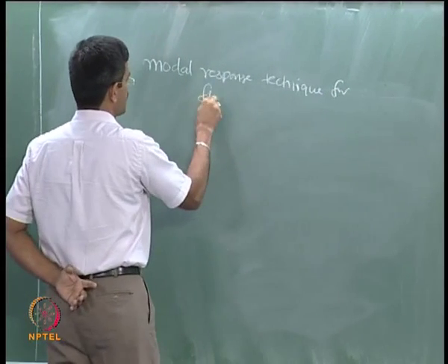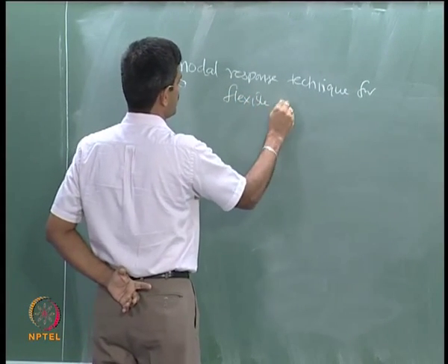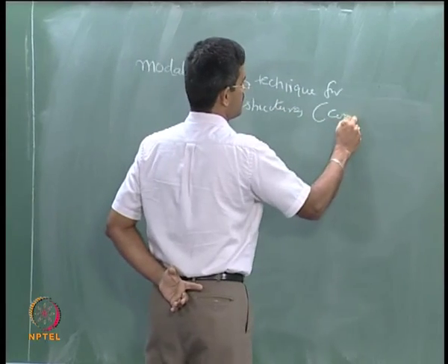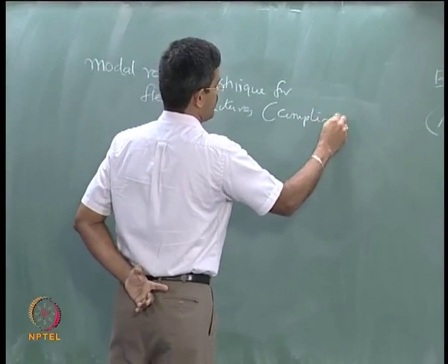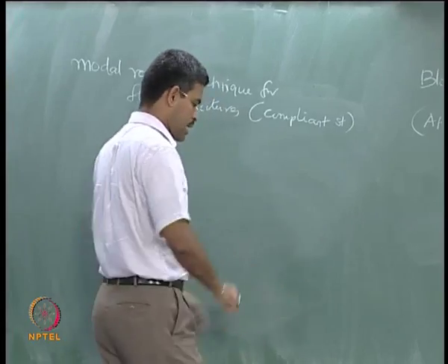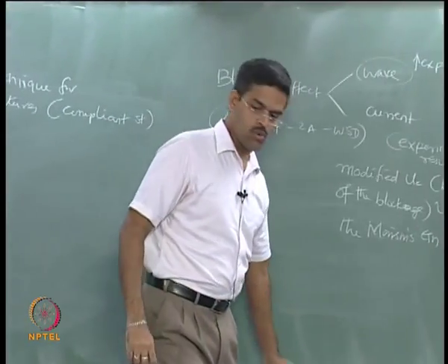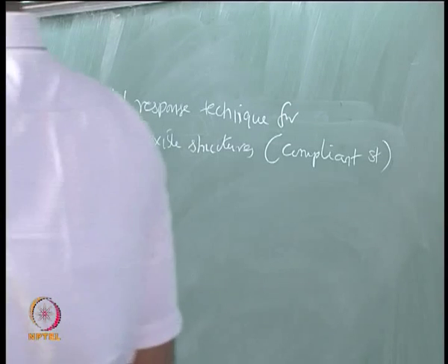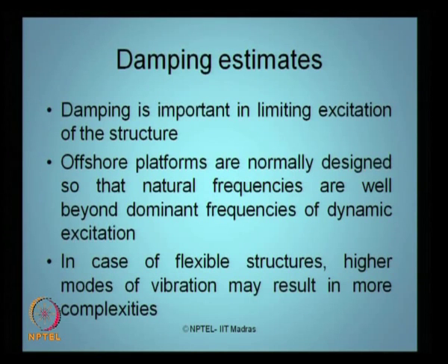For flexible structures, or I should say compliance. We will work out an example of how to truncate the modes etc. later, but we should use this algorithm if you are talking about compliant structures, because higher modes will now participate in the overall response of the structure.